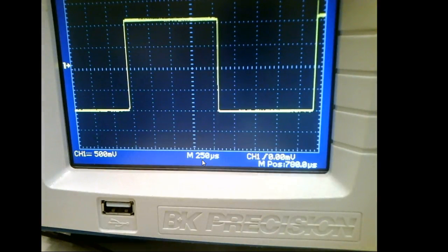So I'd say 500, 1,000, and then if it's 500 millivolts per division, I know each one of these minor divisions has to be worth 100 millivolts, right? Y'all understand that? So it would be what? We ain't got it right yet.